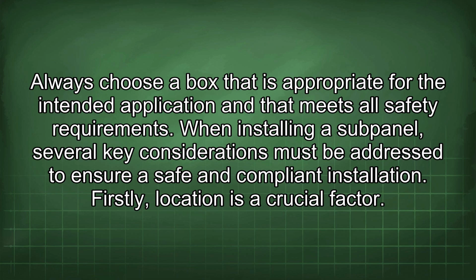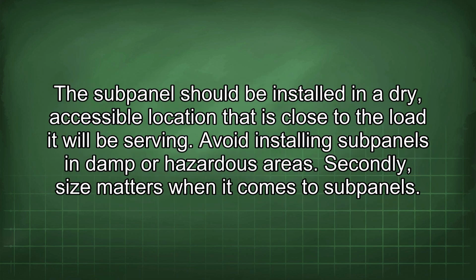When installing a subpanel, several key considerations must be addressed to ensure a safe and compliant installation. Firstly, location is a crucial factor. The subpanel should be installed in a dry, accessible location that is close to the load it will be serving. Avoid installing subpanels in damp or hazardous areas.